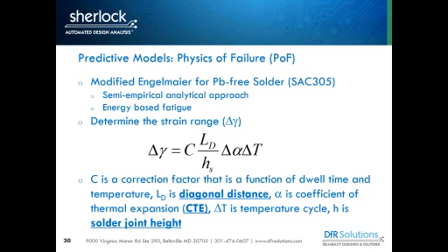So just some basics on the physics of failure behind solder fatigue. Really, Engelmaier was the first one that came up with this, and it may have gone back even further, and it's a standard type of model. But really, we're looking at a semi-empirical type of analytical approach, where fatigue data in general is empirical.